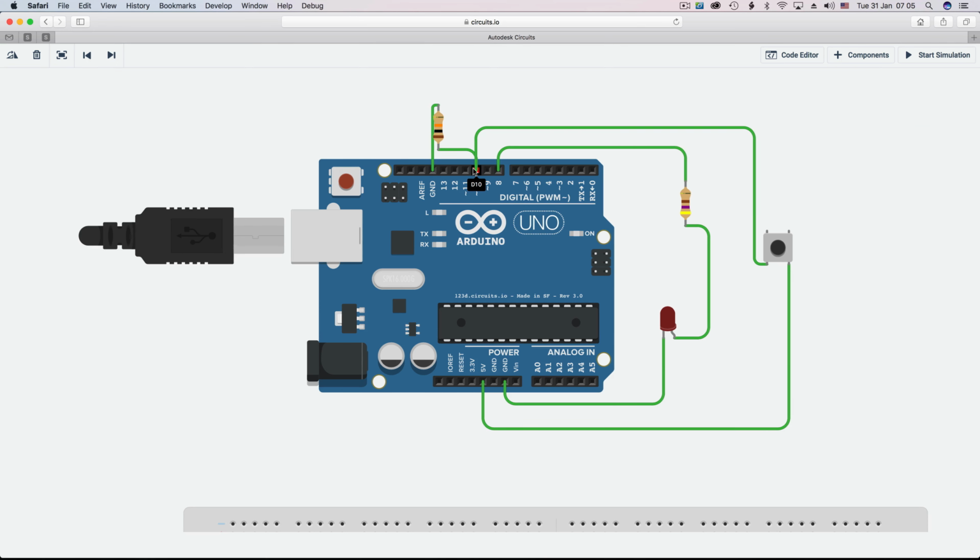This is so that we can make sure that the pin value will not change state when it's at 0 volts. When a pin is not pulled down or made ground through a resistor, it is called a floating pin. This is a very complex theory of why this happens, and I will explain it in a later tutorial. For now, you just have to understand that you will require this resistor for your circuit to work properly. Next, wire up your LED as we did in tutorial number 1, because we will be using very similar code to make the LED turn on and to make the LED turn off.